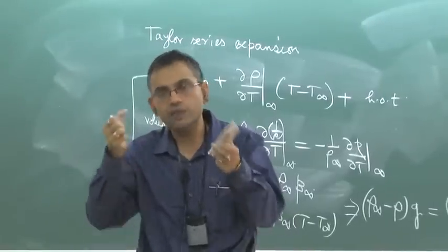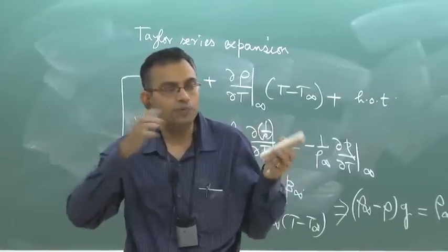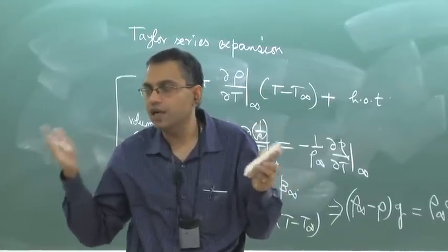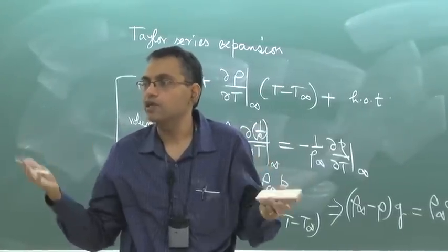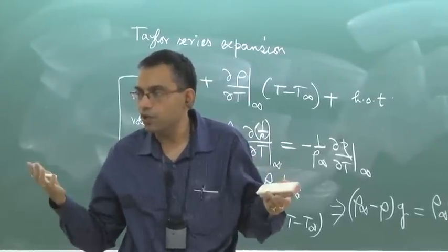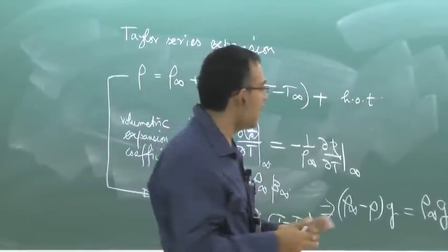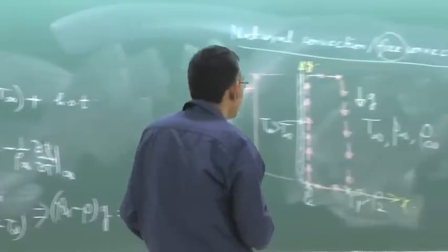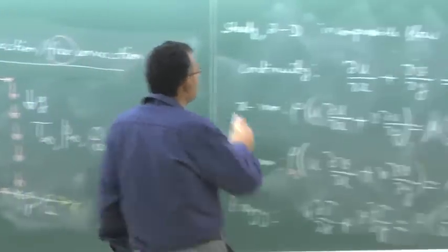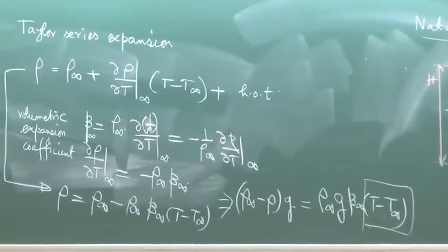Maybe there are some effects of forced convection, there are effects of natural convection. So together, forced convection and natural convection, if they are there, that is called mixed convection. So in a mixed convection, which effect is important and which is not, that you have to figure out. So to do that we will first not consider the analysis of these equations, but we will just non-dimensionalize the equations.